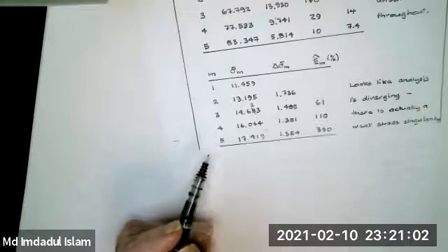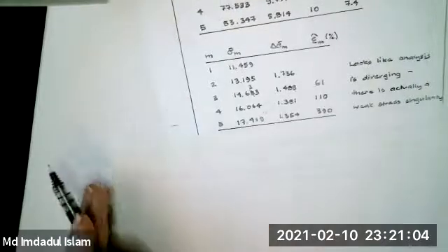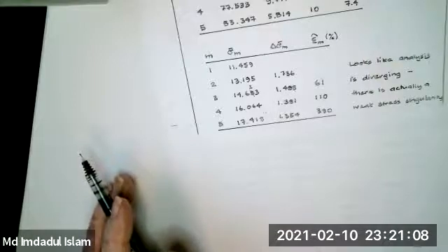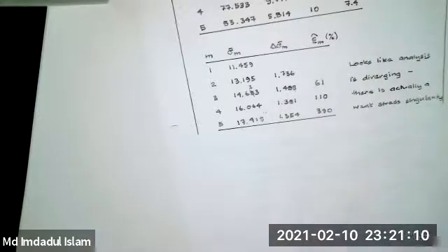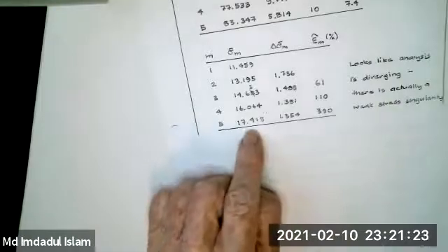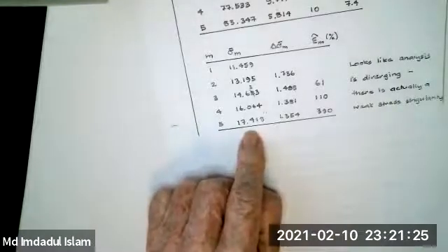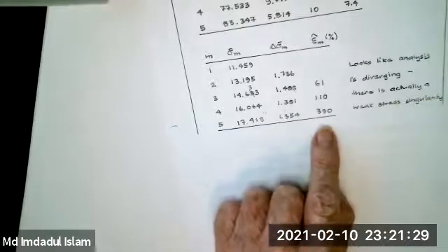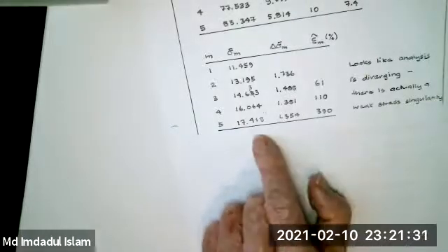Well, what's happening here is this problem, we deliberately did a problem that had a very weak stress singularity. And what happens with these weak stress singularities, you can't report a finite element value if you've got a stress singularity. You can't report a finite element value unless you're converging. Well, here you could report this and say it's converging according to our converging requirements, but the error is unacceptable. Okay, and so you wouldn't report it.